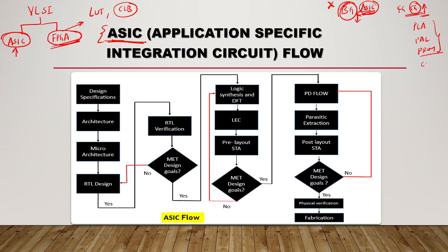Above this, there are CPLDs, complex programmable logic devices, and next you will get FPGA. CPLDs are made with EEPROM, so whatever program is there will be retained in the CPLD. But FPGA consists of SRAM only.